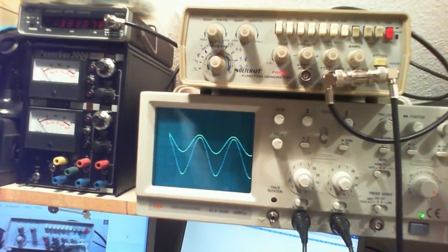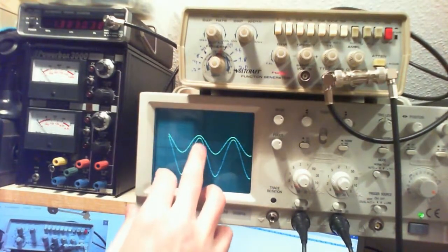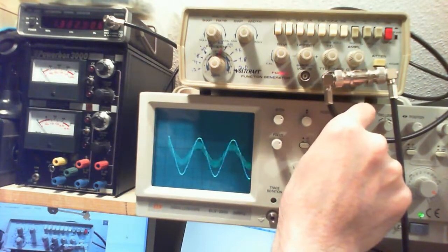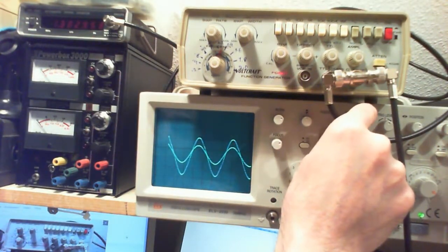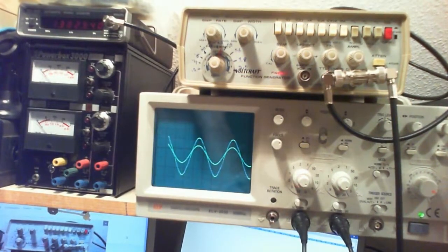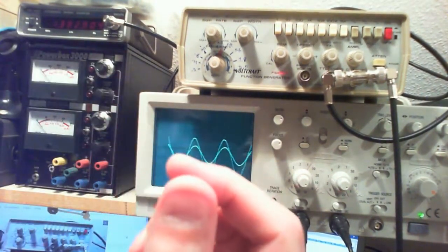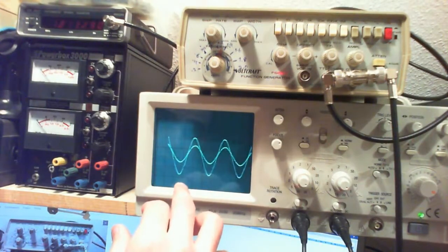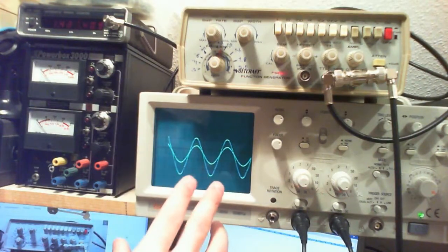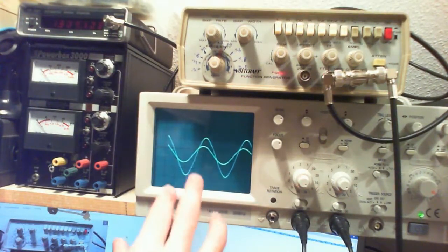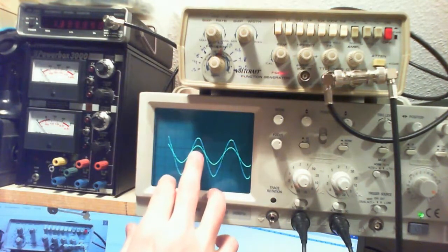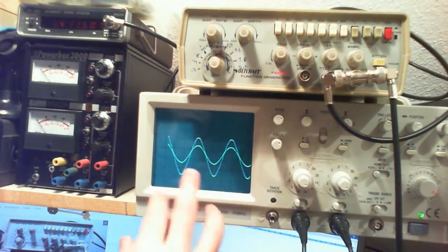Right now this is my output voltage, the one that I'm moving, and if I increase the frequency from this point, the output is getting smaller and smaller. At the same time the phase shift is cancelling itself out at this point, which is about 1.34 megahertz.